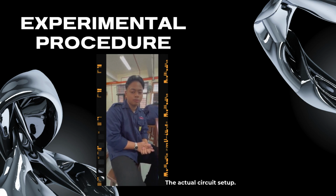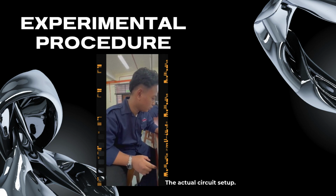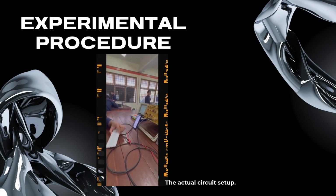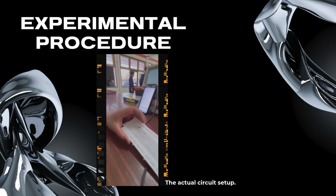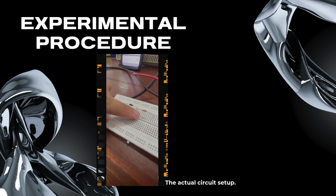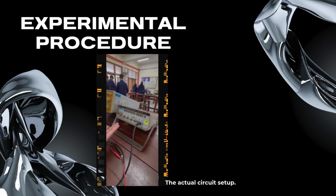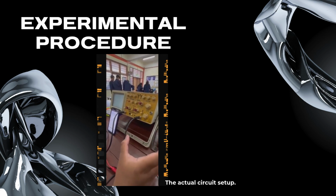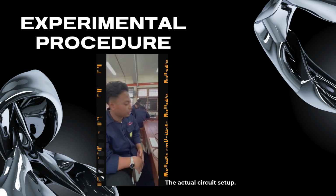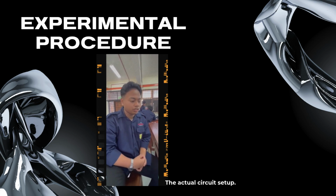Of semiconductor PW3, and then I want to show you how to do the application of diode in half wave rectifier. So the circuit I have set up is this: this is the diode, and this is the resistor. And then we are using the function generator and also the oscilloscope. Both of these machines have been calibrated by myself. And also we are going to proceed to the process.